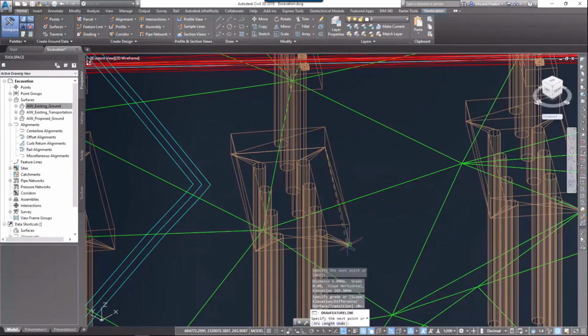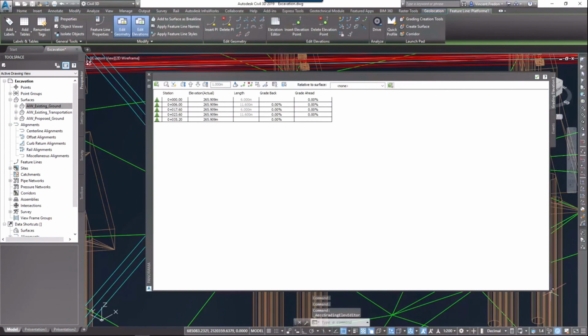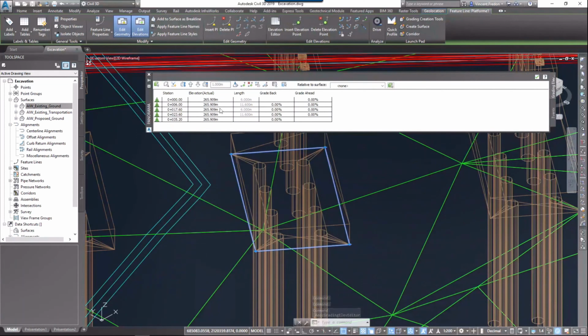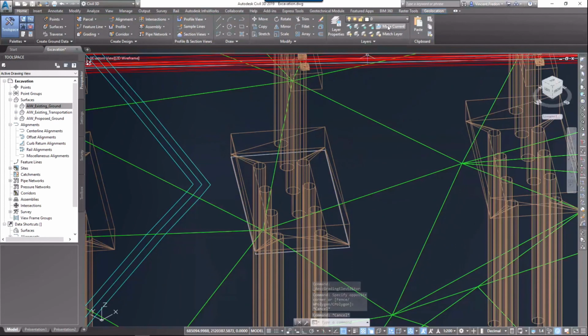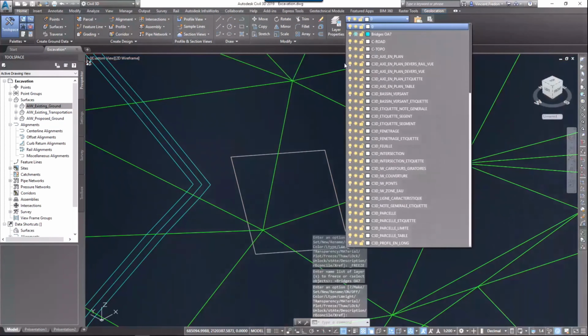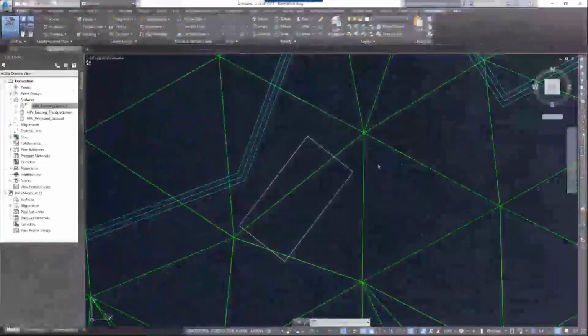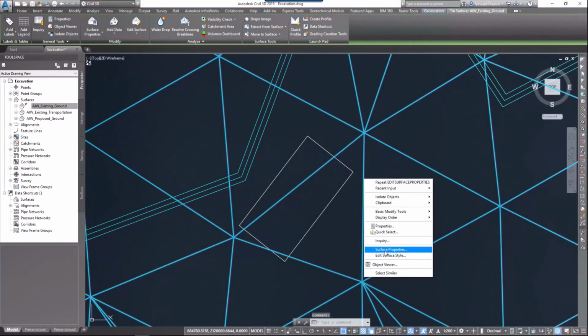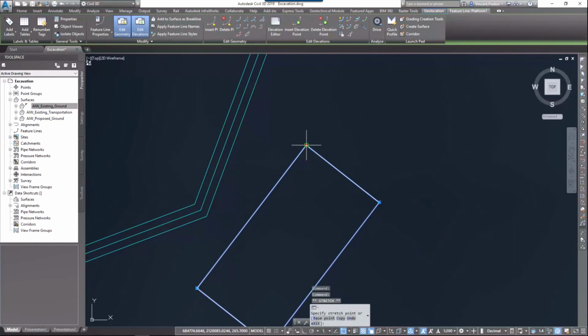And I create a feature line using the shape of the foundation from InfraWorks. This feature line is very easy to manage in Civil 3D. It's like a 3D polyline, but with more properties, easier to manage than a 3D polyline. From this feature line, I will create the shape of the excavation, and it's the base for the grading creation in Civil 3D. All the gradings will be created from this line.